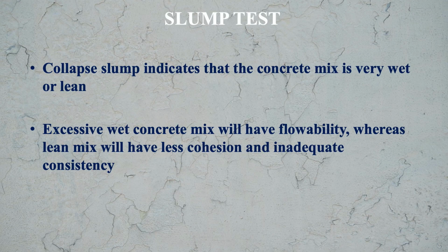So you can say that the concrete mixes showing the shear slump or the collapse, these two are not workable concrete mixes. We have to have the true slump to get a workable concrete mix. An excessively wet concrete mix will have flowability, whereas a lean mix will have less cohesion and inadequate consistency. These properties will be shown by such types of mixes.